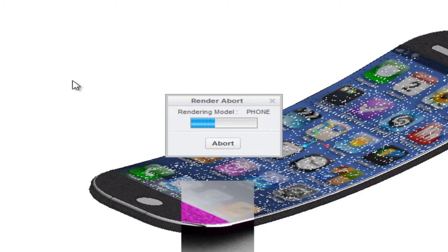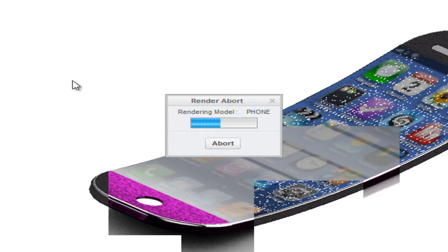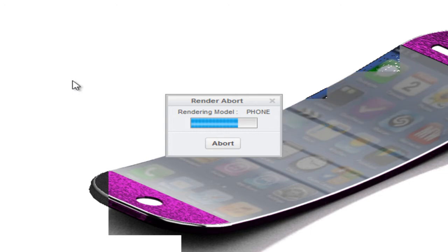If you want to create a high quality JPEG, there is the option to do that within the software. And all you do is under render setup, there's a little tab that says output. And in that you can select where it outputs, and by default it's going to output to the screen. All you do is click on that and say you want to output to a file, and you point Creo to the place where you want the file to be created. So as soon as it's rendered, I'll just quickly point you in that direction.